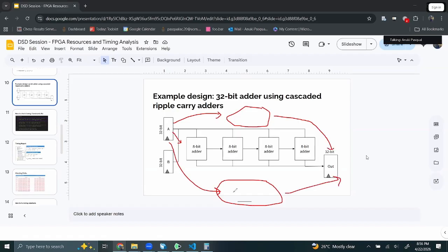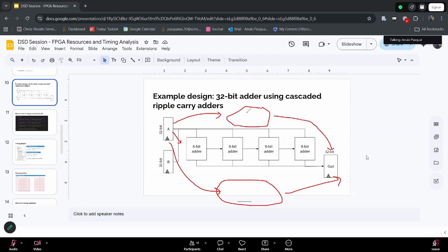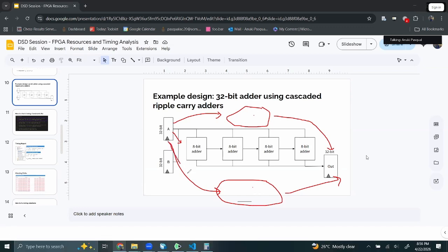If the adder and subtractor are fast and the multiplier is slow, then the propagation delay will still be the maximum. We are considering maximum propagation delay for the setup time. So if the maximum delay is too slow, it will still cause a setup time violation.